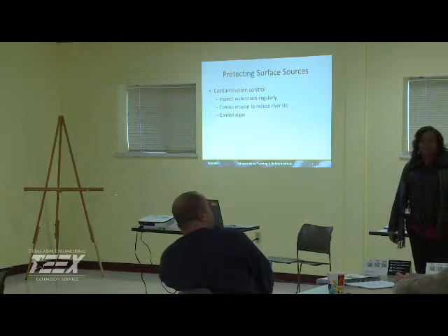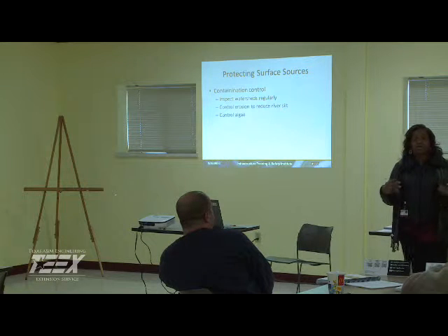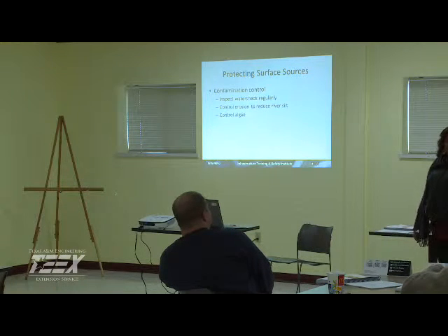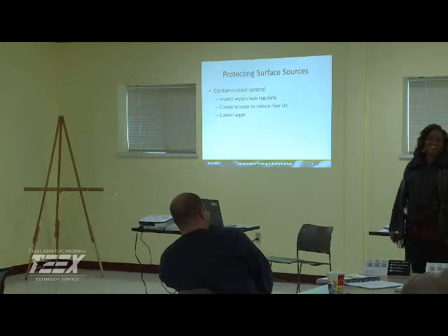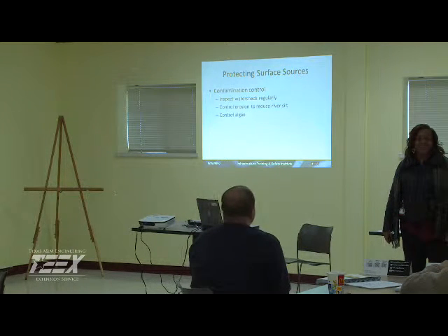0.1 to 0.5 milligrams per liter. And again, we keep it low because it is very toxic. One of the things that you probably should do also is read the SDS, safety data sheet. There are some handouts from the EPA too that make suggestions for different types of algae and what kind of dosages are effective. So you have some sort of guidelines.